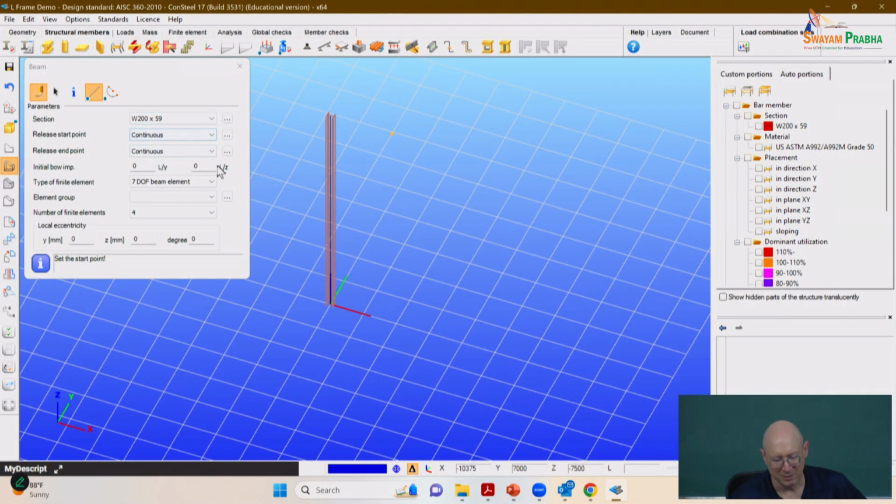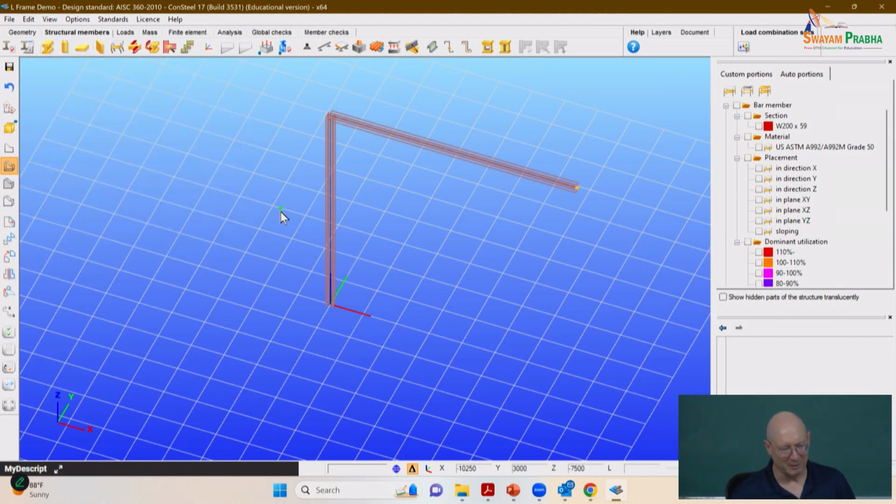So if I come here, I select the top of the column, I drag my mouse button out, let go of the mouse. If you've got your hand on your mouse, it'll screw up your X, Y, Z. X, 7500, Y, 0, Z, oops, X, 7500, I hit X accidentally, Z, 0. Return. All right, so we've got our beam and our column. Never defined any nodes.